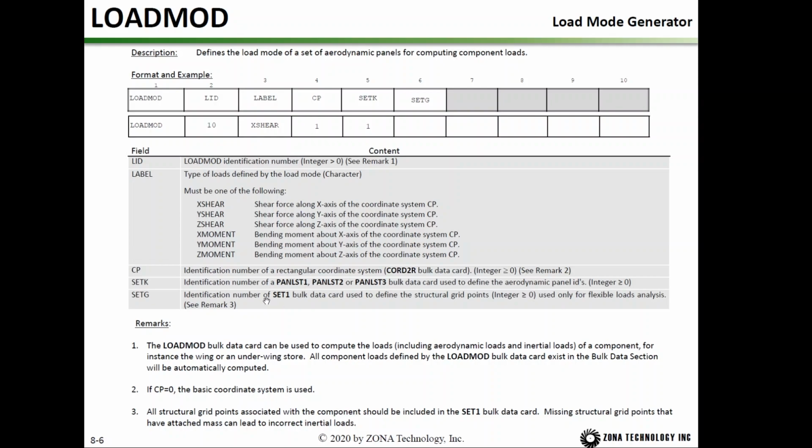And SETG refers to a SET1 card. In the SET1 card, you specify the IDs of the structure grids which are within this component loads region, and then it is used only for flexible loads analysis.